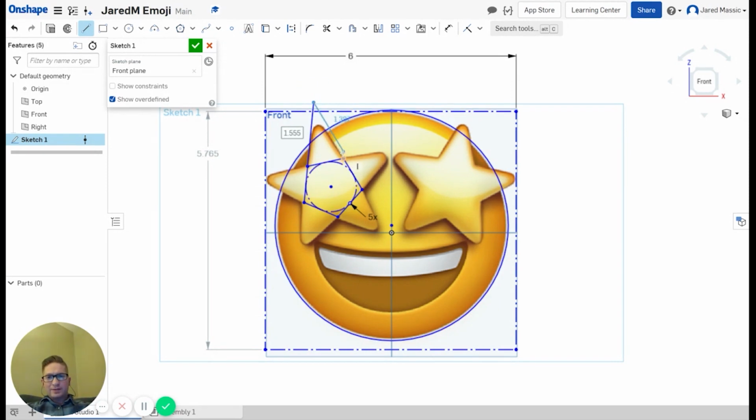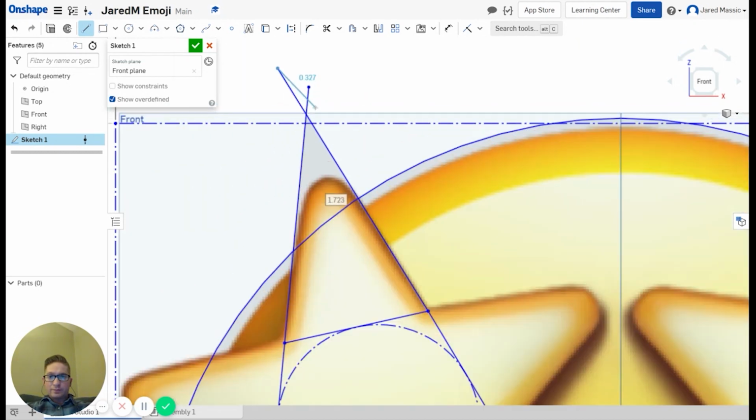I didn't really get the exact angle I wanted, so I'm going to double click, and that stops my line. I can come up to this little scissors and trim that line back. I'm going to click on the scissors, go back to the line tool, click on this, and just intersect it. Now, if I zoom in, I'm going to click on the scissors. I don't need to double click. I could just go right to the scissors. But I could click and click, right?